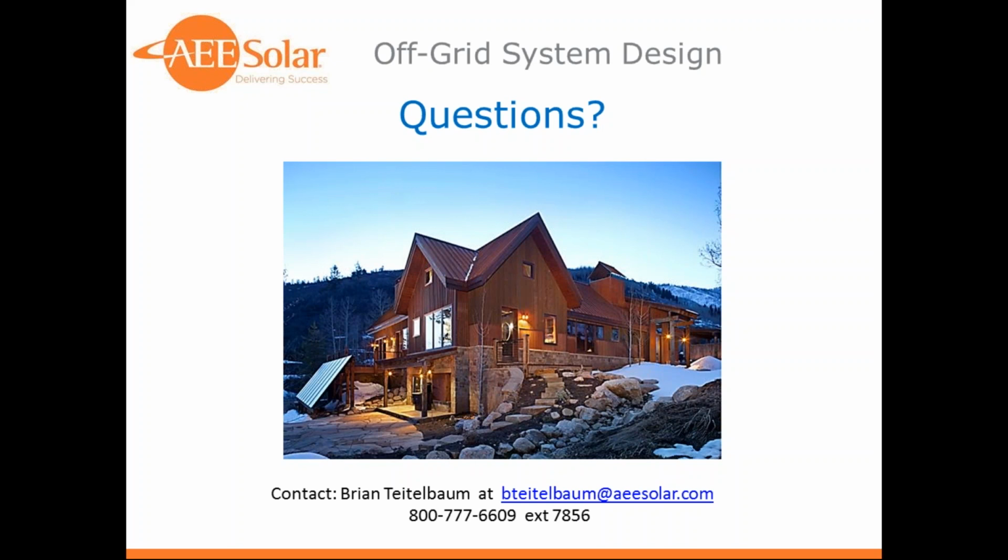Seasonal cabins, well, it depends on the season, of course. If it's the winter season, like a ski cabin or something, you're pretty much designing for that period of the year. If it's summer use only, then you can really look at the peak sun hours for when it's being used and figure that there's less energy. However, you also want to keep your batteries charged over the winter. If there's no occupancy for, say, 6 months of the year, you want to make sure that there's some charging on your batteries. You don't want your batteries to be just sitting there with no charge. They may be prone to freezing. Certainly, lead-acid batteries are damaged if they're left in partial states of charge for long periods. So you want to have some charging there.